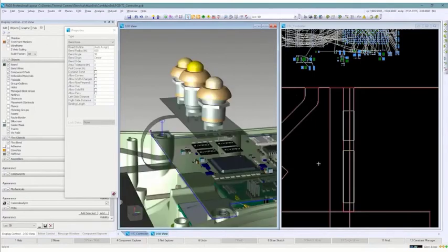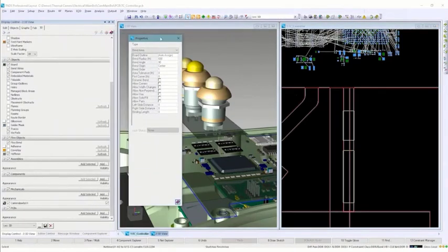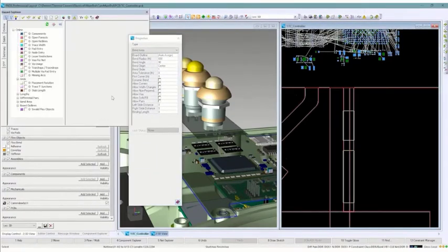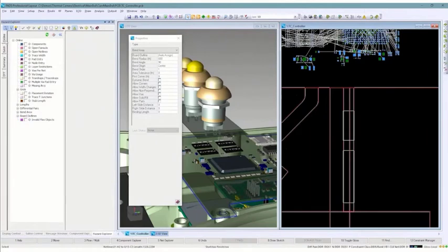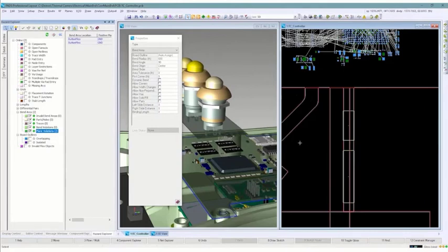All right, now let's move on to some other flex bending dynamic verification capabilities that the tool provides. To do this, I'm going to open up our Hazard Explorer. Go ahead and mount that real quick here. And with our online DRCs turned on, we have bend area verification. So it will tell me if I have any issues related with the bend areas when I place components on the board, or if I'm routing and putting vias in, or traces. Like I mentioned earlier, traces cannot be routed at 90 degrees within a bend area.